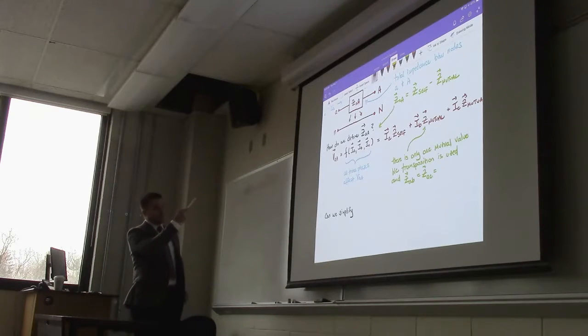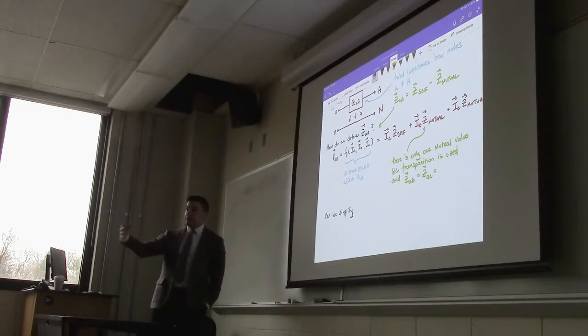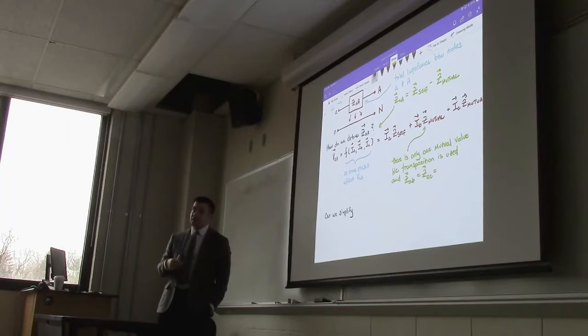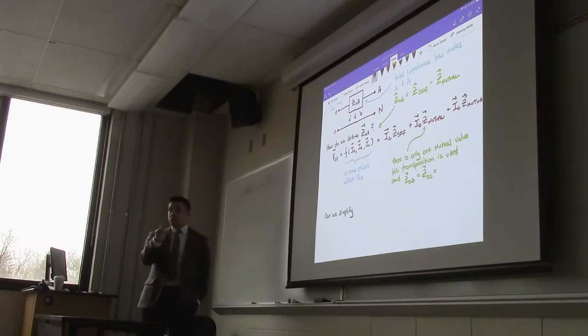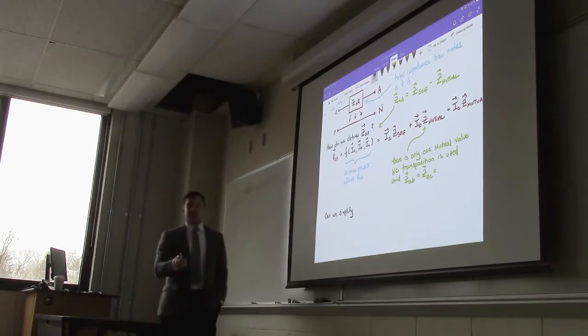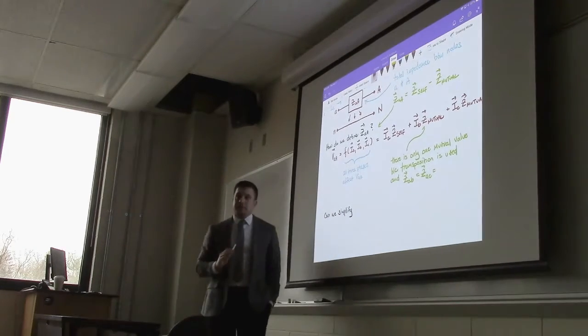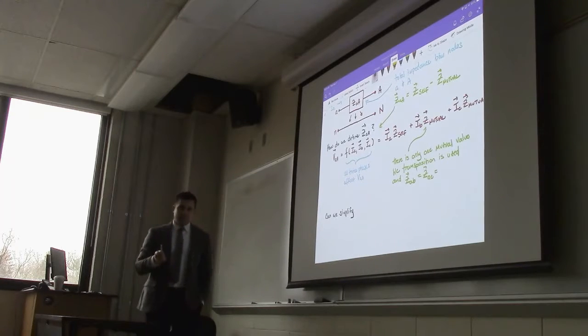That's just the impedance of that line, the impedance that, like when you work with DC circuits, would be the self-resistance, just a resistance along the line itself. The mutual is represented by, most times, mutual inductance that you're experiencing. So the voltage drop associated with the self-impedance is only felt on that line itself. Does that make sense? Yeah.